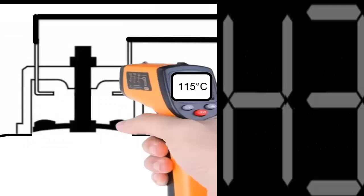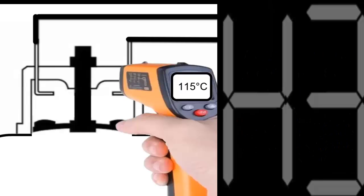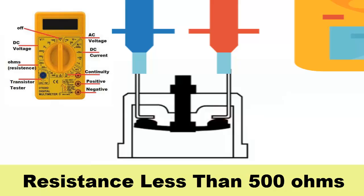6. With a multimeter in ohmmeter mode, measure the resistance between the two thermostat cables. A value between 1 and 500 ohms indicates that the thermostat is functioning correctly. A value higher than 1 kiloohm means that the thermostat is damaged and needs to be replaced.